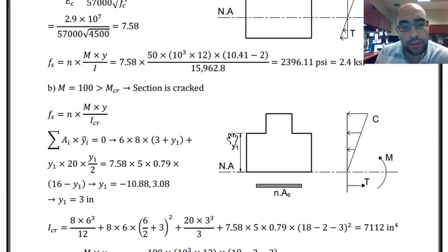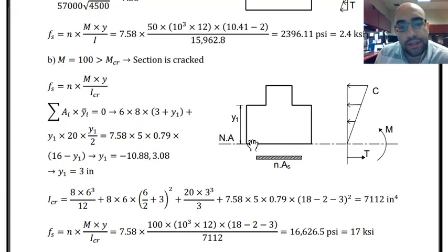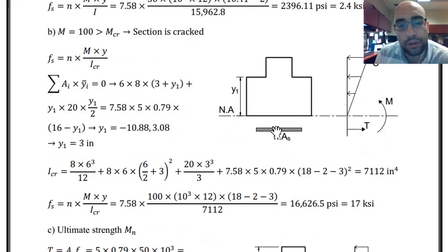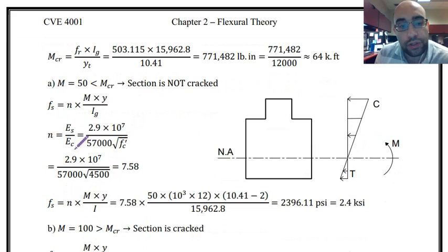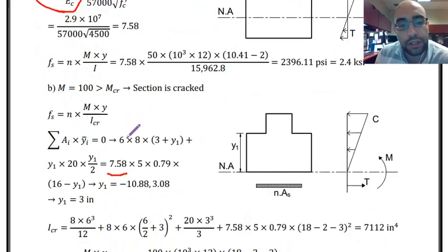So over here you can see on the other side we have the reinforcement, or steel, and I have to just calculate the moment of area that we have on the other side. That is the amount of steel area that I have, that is 5 multiplied by 0.79. This n is the ratio of the Young modulus of steel over the Young modulus of concrete.